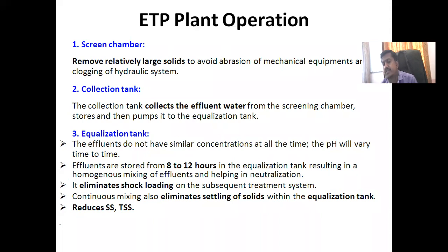In the equalization tank, what is the purpose? It results in a homogeneous mixing of the effluents and helps in neutralization. Okay. It also eliminates the shock loading on the subsequent treatment systems. Okay. So here we are going to store the water for 8 to 10 hours in the tank. And because of this, त्या टँक मध्ये साचवल्यामुळे ते वेस्ट वॉटर स्टेबल होतं, एक होमोजिनियस मिक्सचर त्याचं तयार होतं. ठीक आहे. And that will help us for the further process.